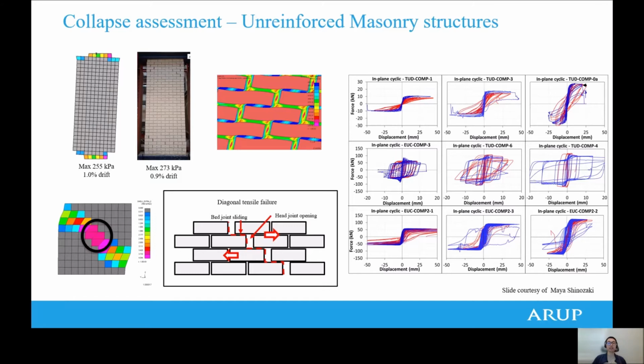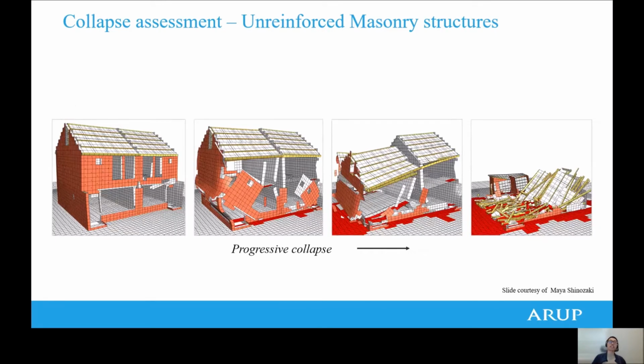With that, combining with the existing advanced numerical modeling and solver capability of LS-DYNA, we constructed a 3D model of each building and explicitly simulated the performance of the building and the collapse behavior. As you can see here in this LS-DYNA simulation snapshot, the progressive collapse can be explicitly captured in the analysis model, even with the collapse debris present after the simulation. So these two examples perfectly show how valuable LS-DYNA analysis can be in the process of evaluating existing structures.